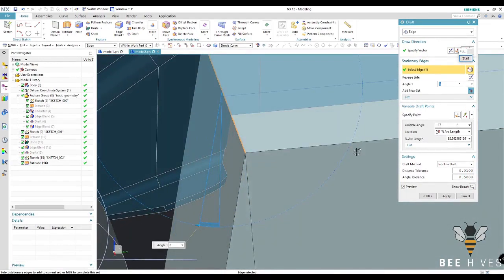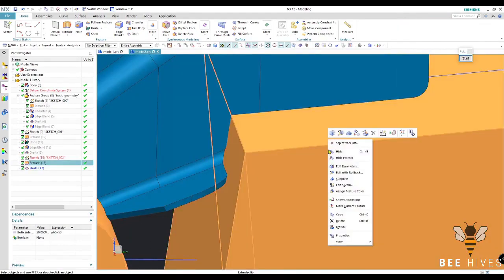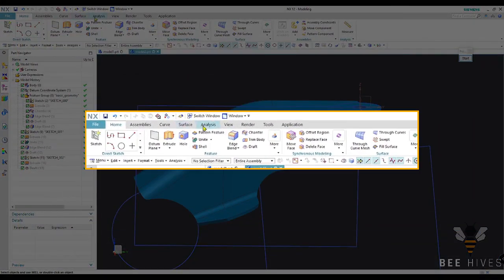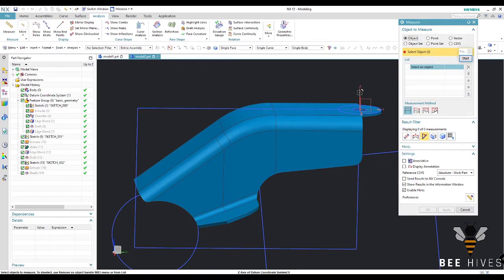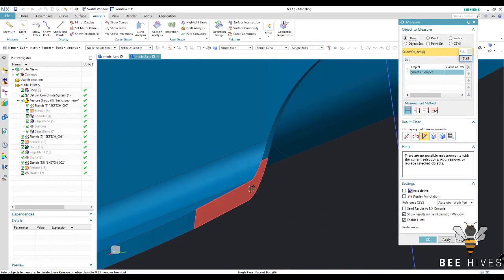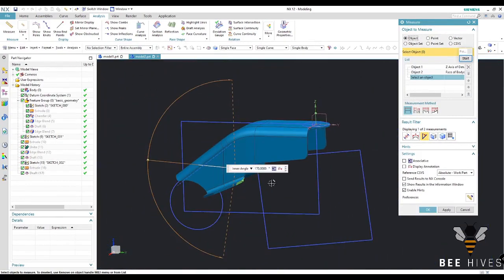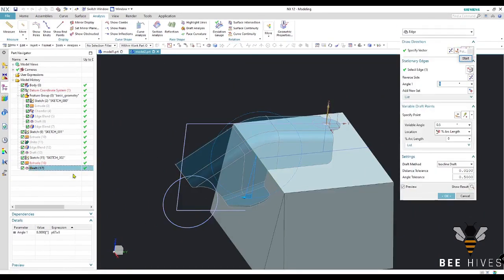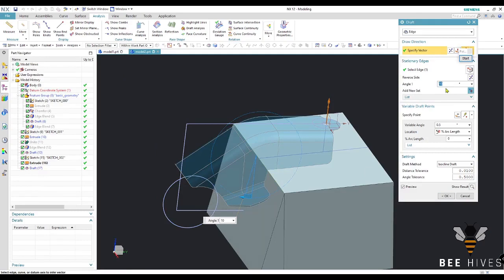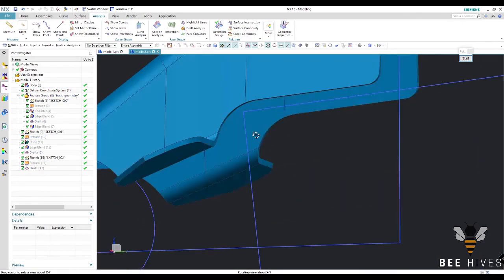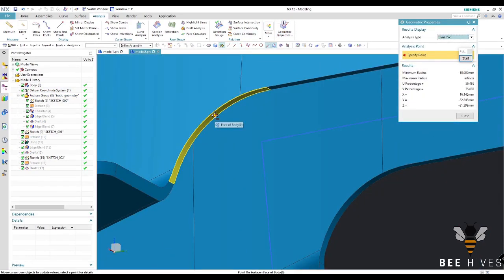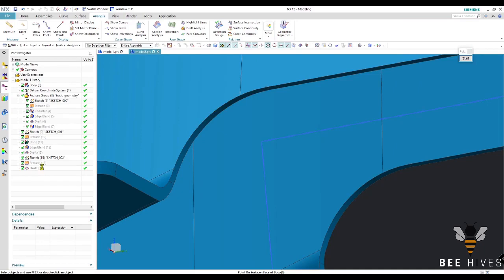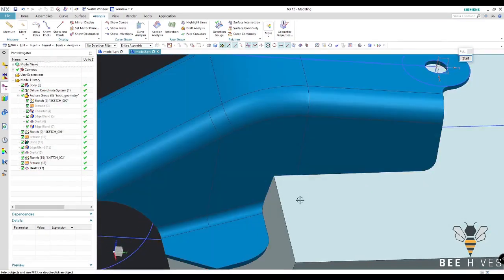You can measure the angle. You can always go ahead with angle measurement. Select object first, axis, and part. It seems to have 170, so it's 10 degrees. So I'm going to give the draft 10 degrees and say okay. Now there's a blend. I'll simply measure the blend to see what exactly the value is. It's radius 10. That's it. So say okay and I'll apply the blend.